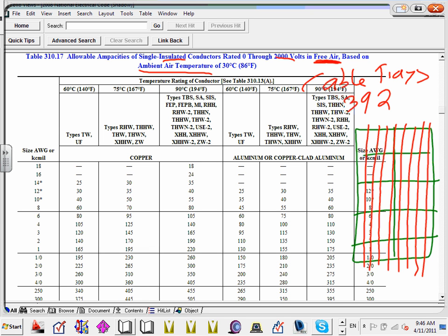And the condition to use this table, there's a few conditions. One, I want to mention it to you. Leave a space of 1 conductor between the conductors. You guys know it's a tray full of cables, but don't pile the conductors on the top of each other. Leave a space of 1 conductor between them. And in cable trays, guys, we don't use less than 1 aught. We can't put anything less than 1 aught in cable trays anyway. We're talking about big conductors.